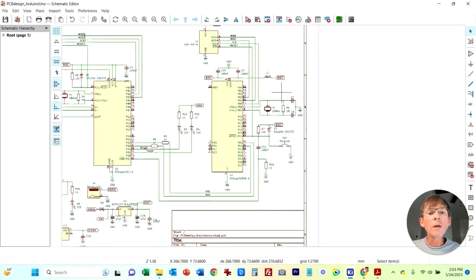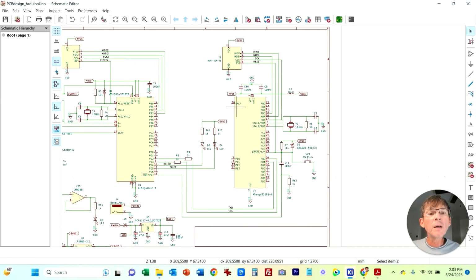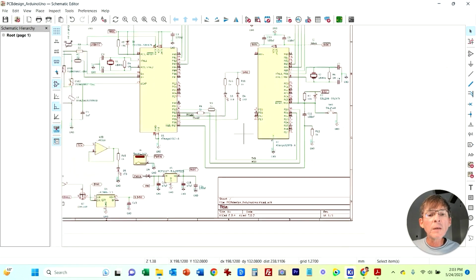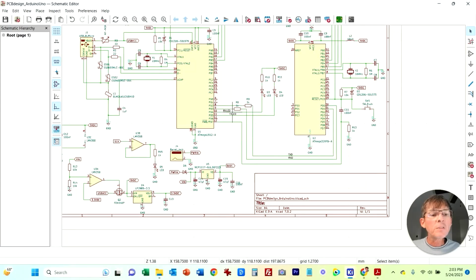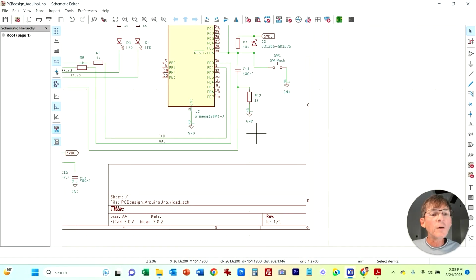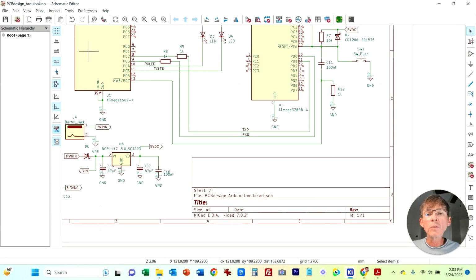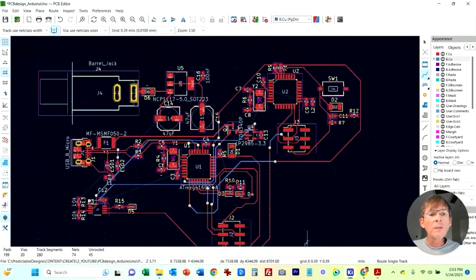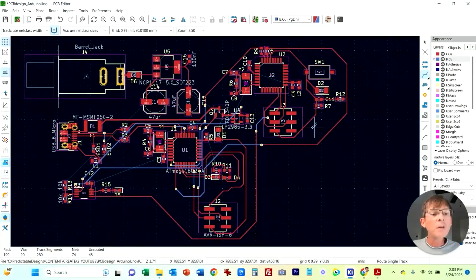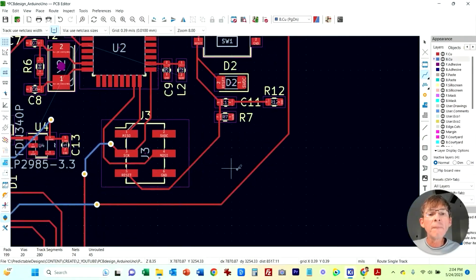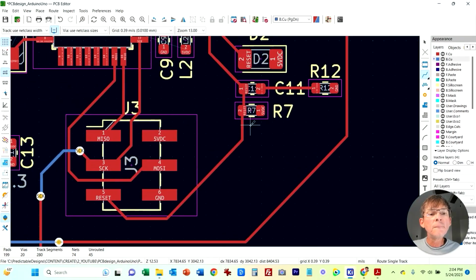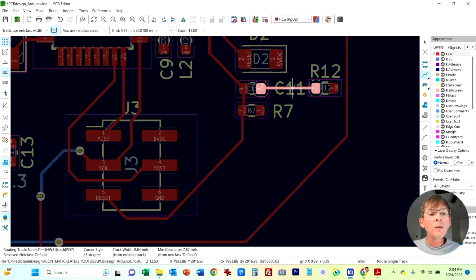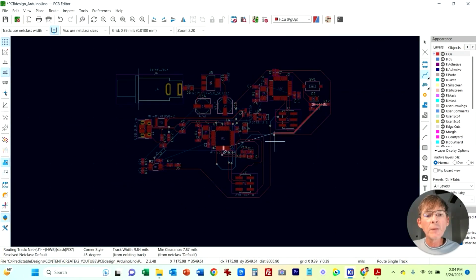All right, let's see here. We've got those. Okay, that's what we just connected. We need also C11. This bottom is going to go over to the first microcontroller. That's for our reset. Let's see, C11. And that's going to go over to here, okay?